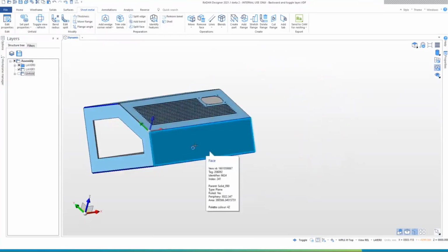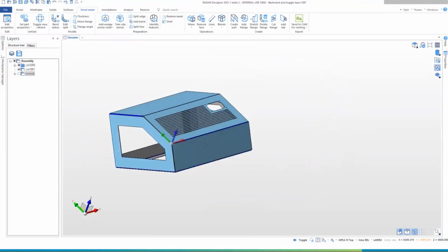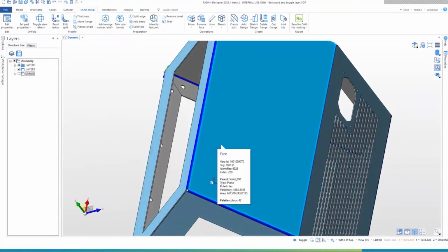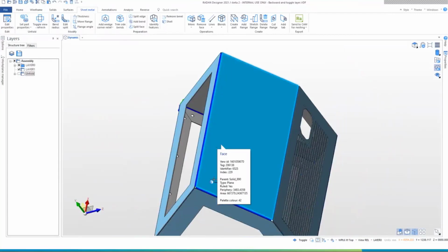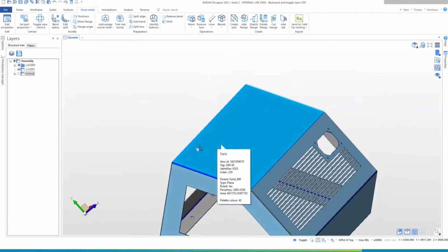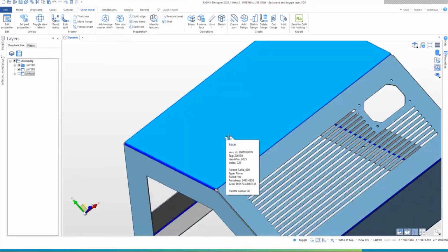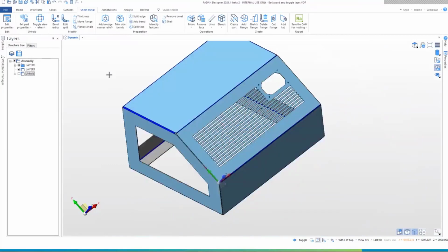As it stands for today, I would say that this backward associativity works on flanges, but I would be careful with modifying bends. To be honest with you, it sometimes works, sometimes doesn't. As of this release, backward associativity works on flanges.